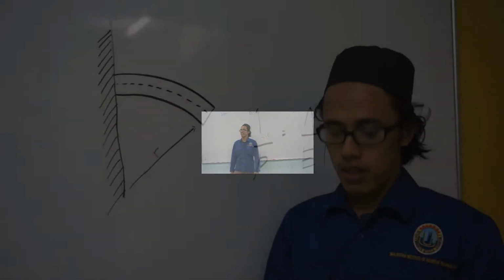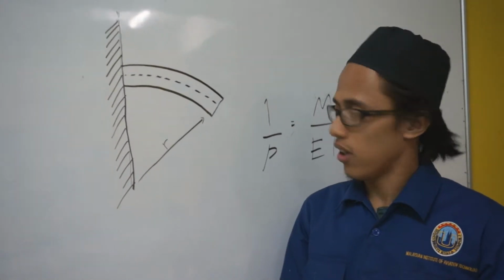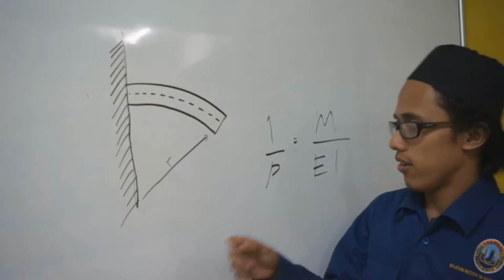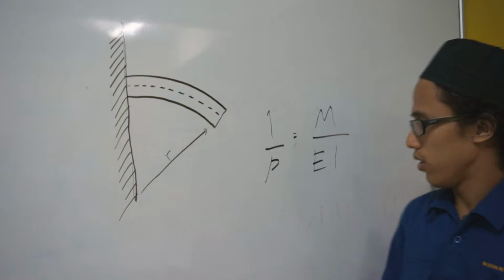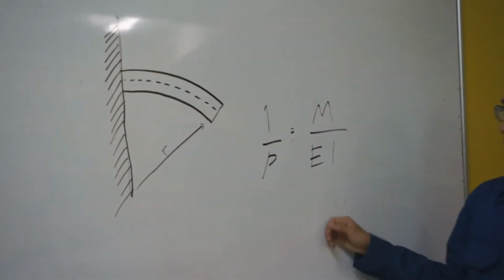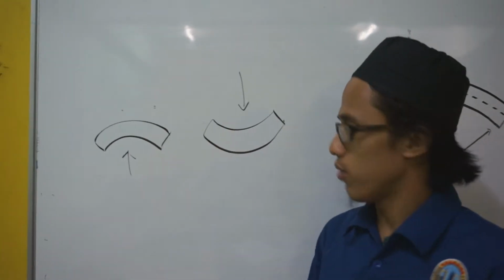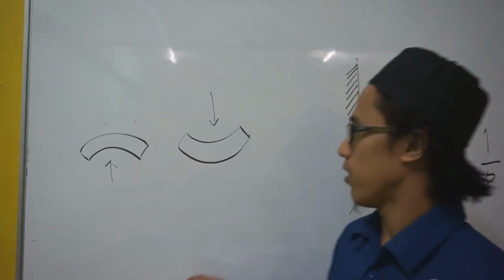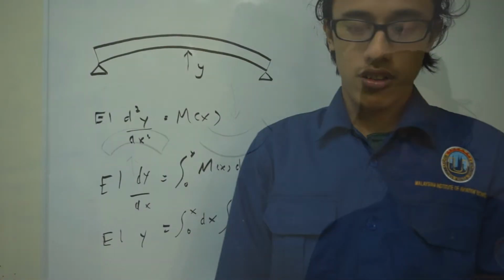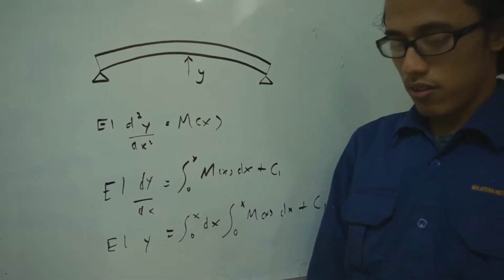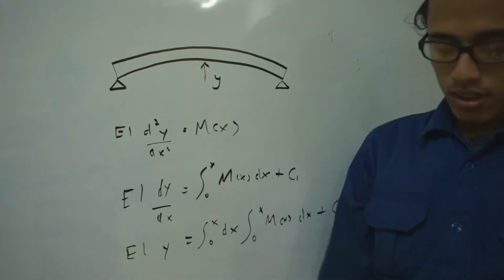Motion due to bending moment is quantified by the curvature of the neutral surface, like this. And to calculate the radius of curvature, we use this formula. The beam is concave upward where the bending moment is positive, and concave downward where the bending moment is negative. Curvature occurs where the magnitude of the moment is at maximum, in this case in the middle part.